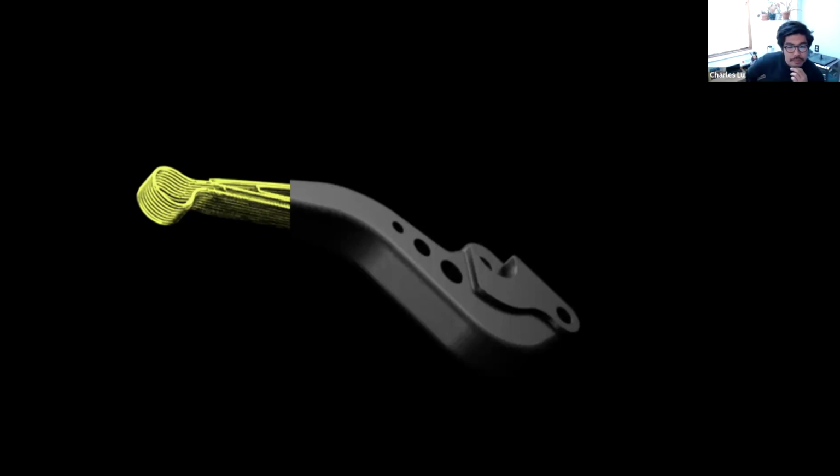Yes. See what the temperatures are like in that area. We have heat deflection temperatures listed in the material spec sheet. So if it goes above that, then you might be out of luck. If it's within that range, you're okay. Another option, if you wanted to make an exhaust shield, is to actually print tooling.